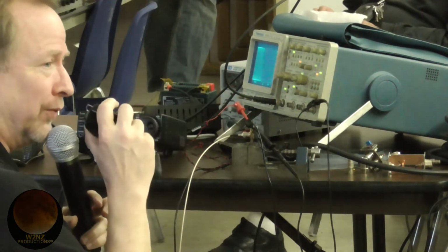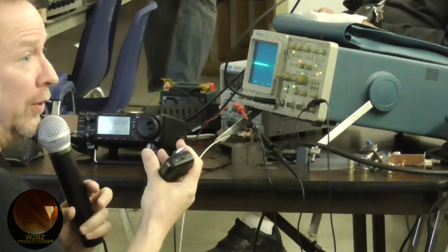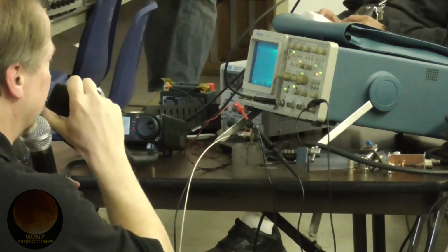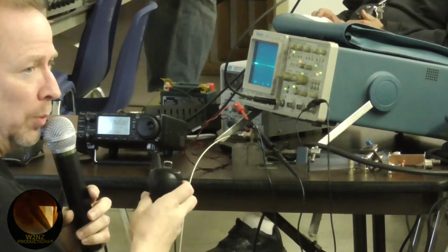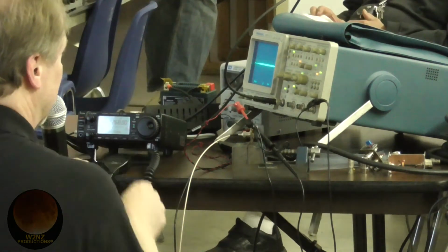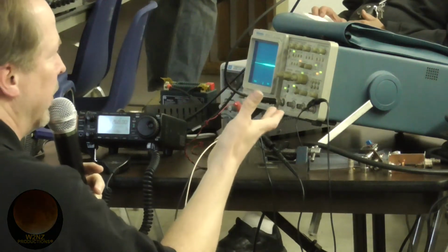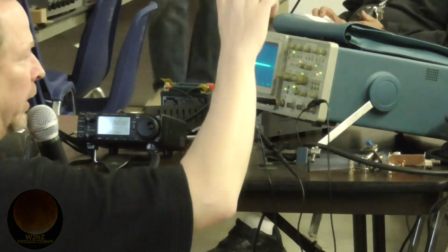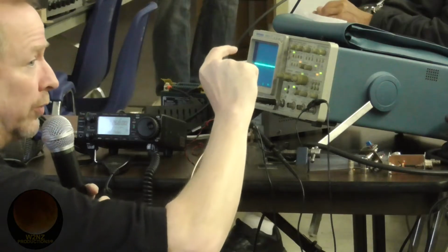Okay, we're measuring voltage, but power is proportional to the square of voltage. So if you cut the amplitude in half that you see on the screen, that's going to be 1/4 of the actual power. And that's the reason, for example, why if you're adjusting an AM transmitter, and say I've got a modern 100-watt rig, and I want to get 100% modulation depth, you want to cut the carrier down to half the amplitude, which will actually be 1/4 of the power.